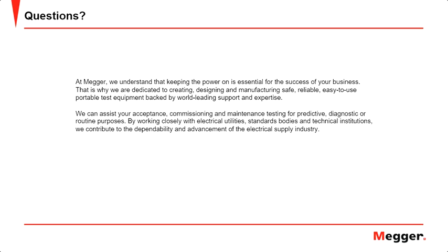Thanks, Chase. While I have you, what is meant by trapped space charges? During a DC test, as he showed, you don't reverse the polarity. So you apply a charge into the cable, whether positive or negative, and whenever you do that, the electrons move. If you don't discharge that for long enough, you don't relax your cable and move those charges back to their normal positions.